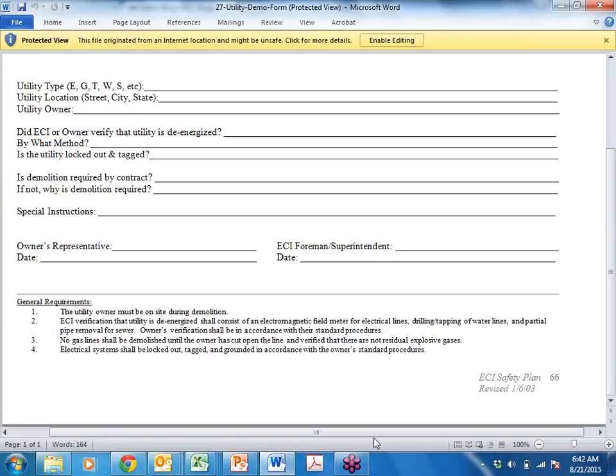On that job, you run into a lot of old infrastructure from past buildings, and when they pull them out and put the new one in, the line stops where the excavation stops. In yesterday's case, we had 20 feet of service coming off a water line, and the gas and water company showed up because they have to decipher whose is whose, since they look a lot alike. That old line was all cast steel line. They used each other's lines for that stuff. Even the older steel line has a newer plastic sleeve in it. You may see it rusted on the outside and think it's old, but get too close and you find it has a liner in it and it's still alive.